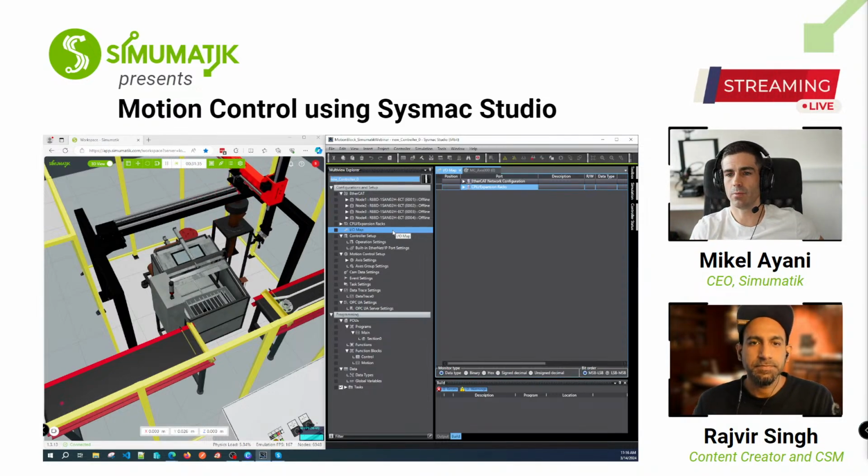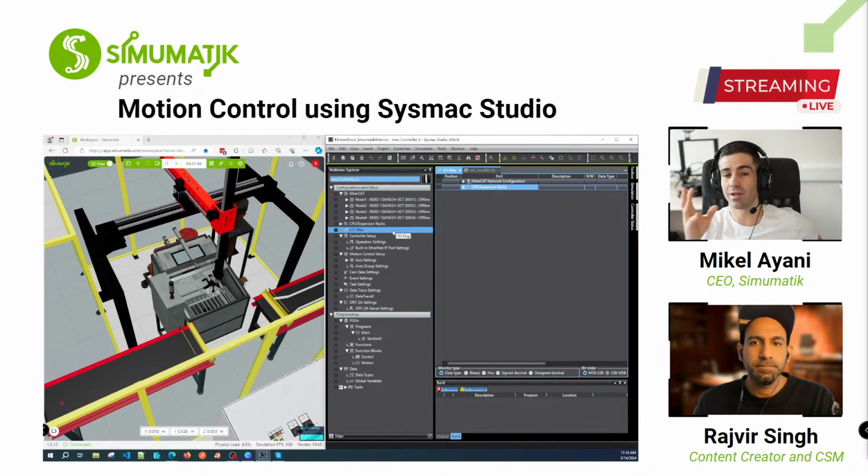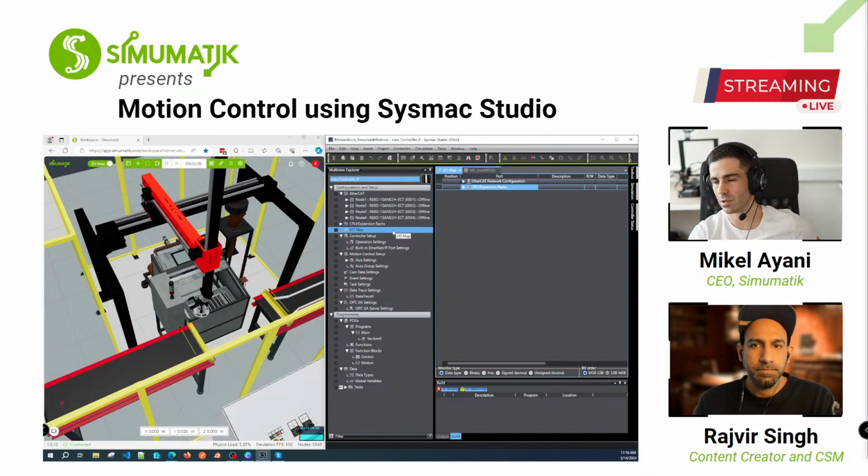Which is good because it simplifies a lot, but kind of hides some issues you may have in the real system, because sometimes you have done bad configurations in the drive, or maybe you have a crash. Your PLC code won't see that crash, and this is why somehow we need to disable that default feature where everything is ideal and try to close the loop.